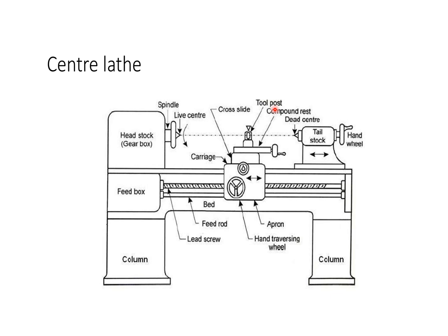Next, feed rod. So the feed rod is a long shaft used to move the carriage or cross slide for turning, facing, boring and all other operations except thread cutting. Power is transmitted from the lathe spindle to the apron gears through the feed rod, through a large number of gears.